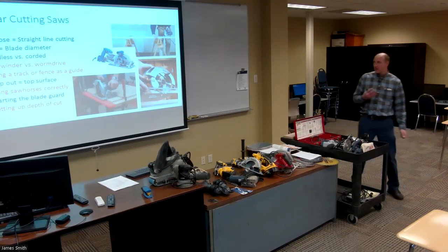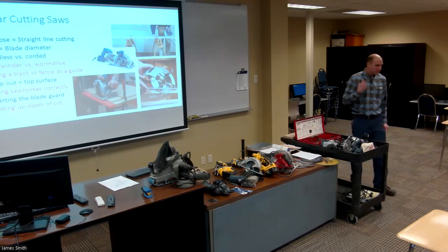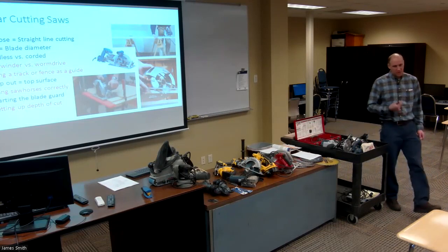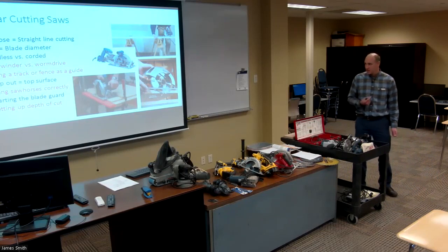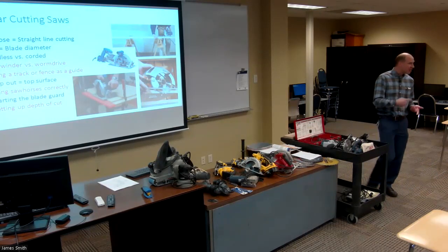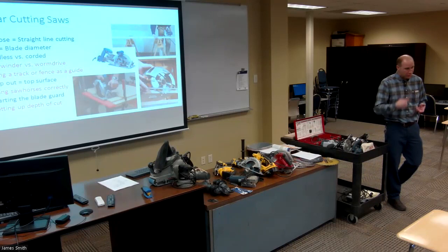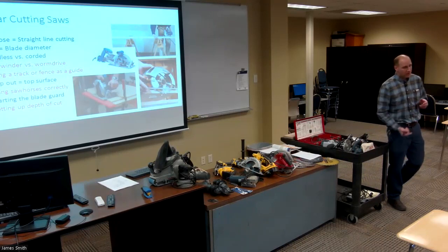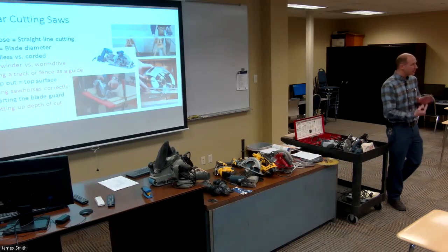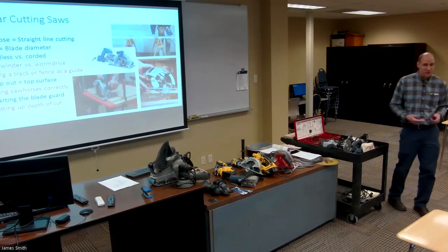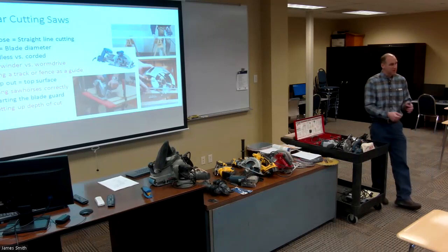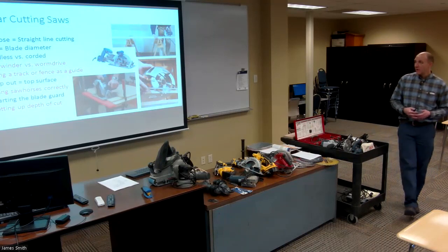And so they're a really valuable thing to learn, but they also incorporate some issues as far as danger, because it's a circular saw, right? And so you've got those 2 different motions. Remember when we talked about how you've got one vector angle of force coming up against the platform, but then you also have one pushing forward. And so you got to be strong with the saw, right? And you have to understand that you can't bind the blade, because that's only going to exacerbate the kickback.